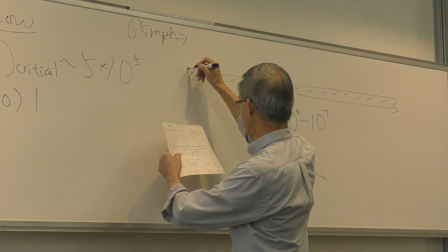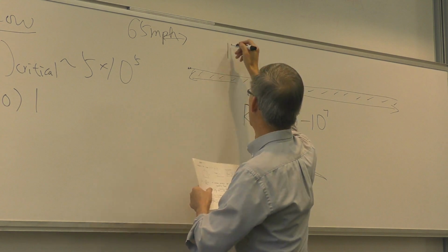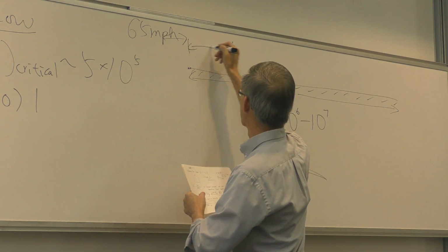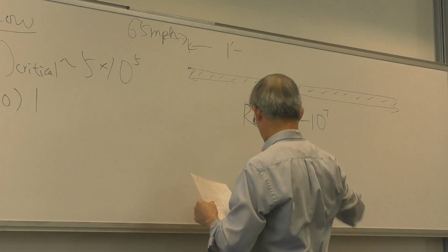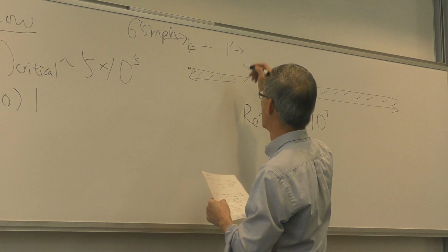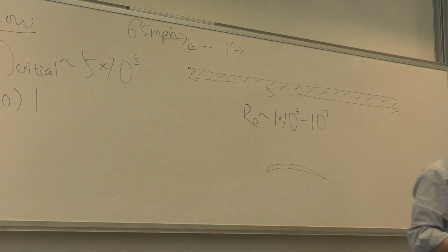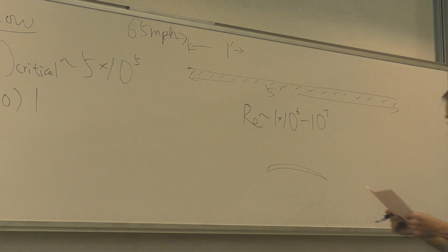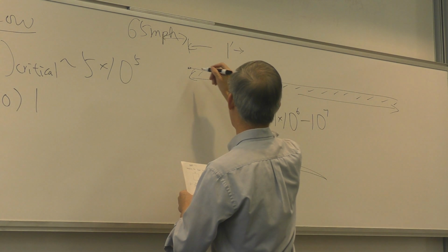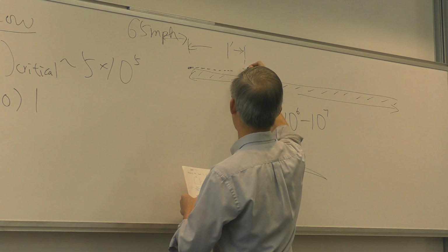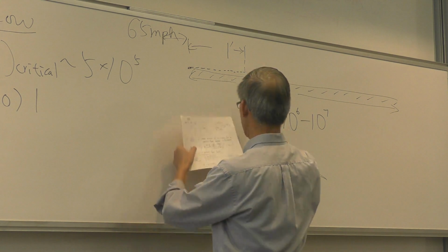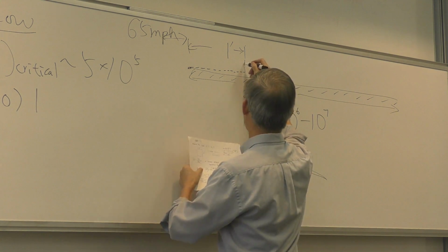What we find is that, and this is approximated so that we can focus on the big picture, out of that 5 feet, approximately about a foot from the nose, the boundary layer will go from laminar to turbulent. We call it the transition. And the thickness at that station, which is the formula you use to estimate based on the Reynolds number, is small.